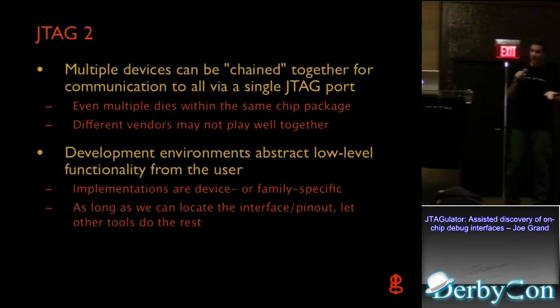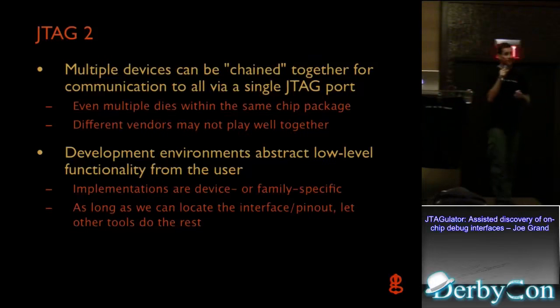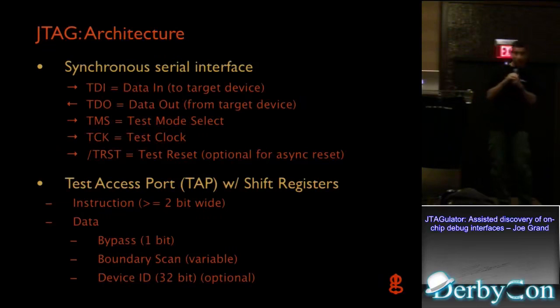And really, the thing to keep in mind is we don't really need to care how JTAG operates. All we want to know are the few things that will enable us to determine the interface, and then once you know the interface, you can just use any off-the-shelf JTAG hardware, whether it's some OpenOCD thing or I'll give you some vendor lists. Usually what I do is, if I'm hacking a board that has a Broadcom chipset, and I find the JTAG interface, I'll try to contact Broadcom or see what people are using to communicate with Broadcom devices, and try to use what the vendor recommends or what they would recommend to a legitimate engineer to work with their devices. It just sort of removes some of the unknowns as opposed to using a general purpose, third-party off-the-shelf JTAG interface that may or may not work. But whatever it is, we don't really care. As long as we find the pin out, there's plenty of other really good tools that will do the rest of the work for us.